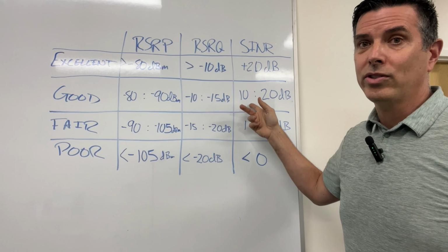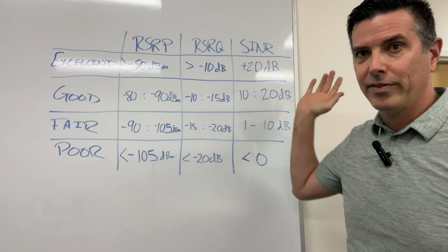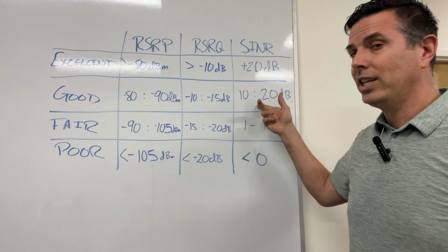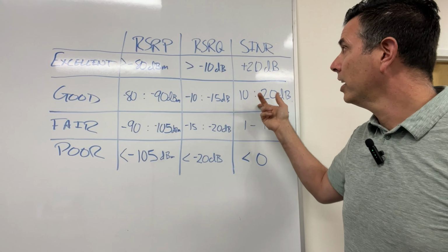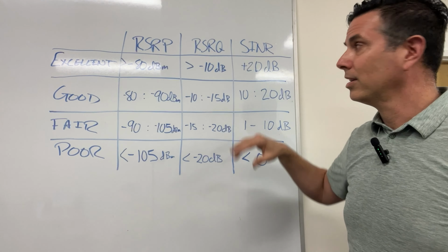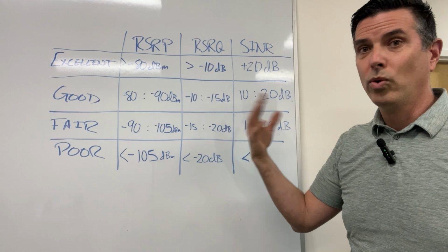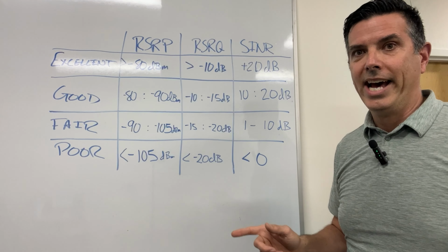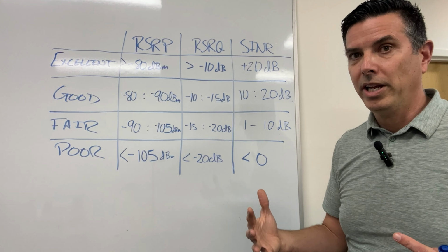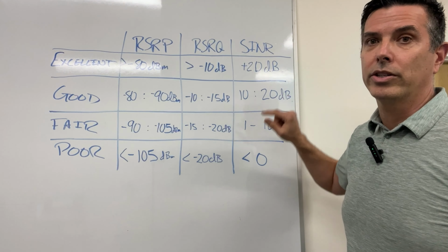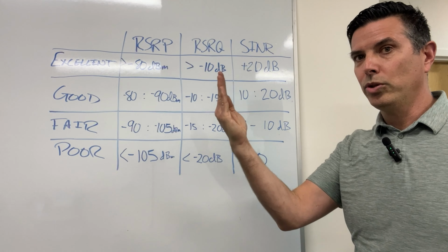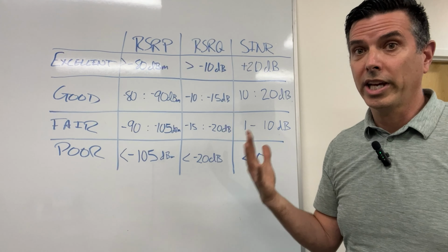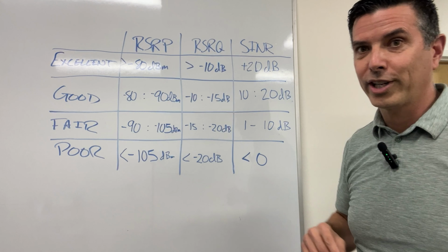If you're good SINR, if you're 10 or above, you're going to be great. 10 or above is okay, especially if you're signal hunting for a good donor. 10, 15, 16 SINR, that's good. That's really good. If you can get your SINR into the above 20 range, 22, 25, 26, that's excellent. Usually in a properly designed DAS with not a lot of zones that cause competing interference, your SINR is going to be very strong. If you hold up your phone right up to a radio and there's no other RF in the area, you will get close to 30. So I will show you what a good SINR plot looks like.